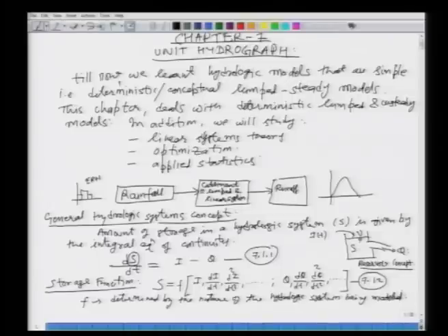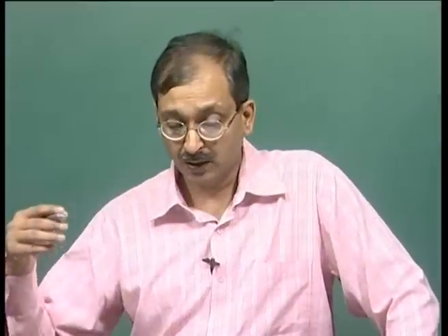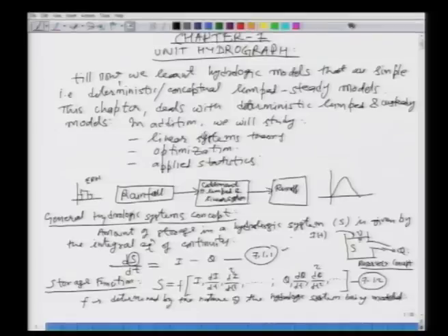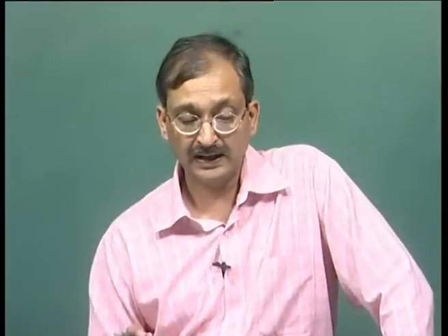All right. So, now you have the input available to us, the rainfall that is falling on the catchment I. Then I have equation 7.1.1, which is nothing but the continuity equation, and I also have the storage function. Let us say I have assumed that it is a linear reservoir. For a linear reservoir, we have seen the relationship between the storage function and the other things. It is S is equal to K times Q. We say that for the linear reservoir, the storage is a function of only the outflow and linear, okay. But we can make the things more complicated.